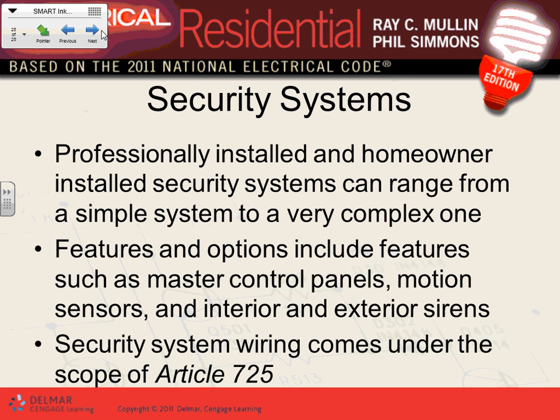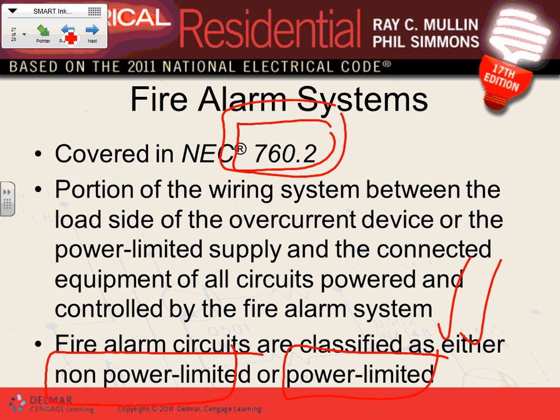760 talks about the wiring methods. By the way, 760 doesn't apply to us, what we're doing right now. This article does not apply to us because we're pulling a combo. A combo is all in one, and they're running at 120. It has nothing to do with it.